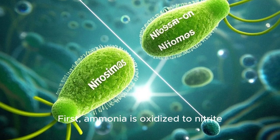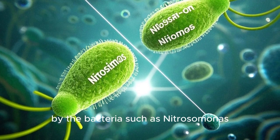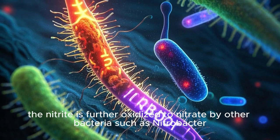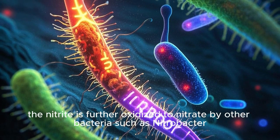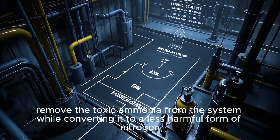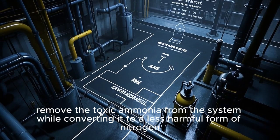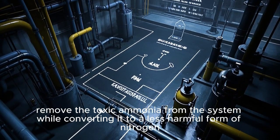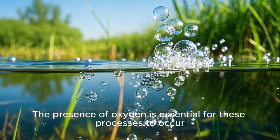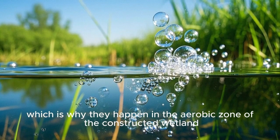First, ammonia is oxidized to nitrite by bacteria such as Nitrosomonas, and second, the nitrite is further oxidized to nitrate by other bacteria such as Nitrobacter. This conversion of ammonia to nitrate helps remove the toxic ammonia from the system while converting it to a less harmful form of nitrogen. The presence of oxygen is essential for these processes to occur, which is why they happen in the aerobic zone of the constructed wetland.